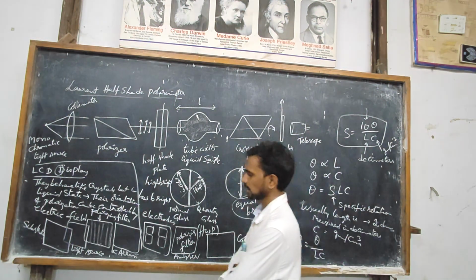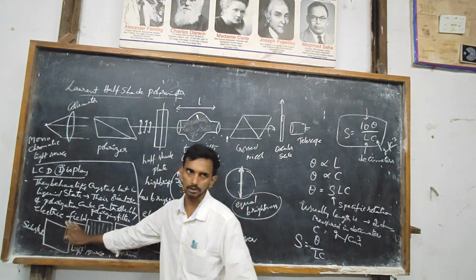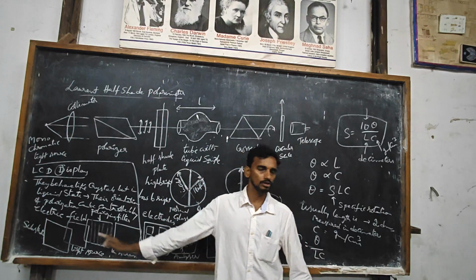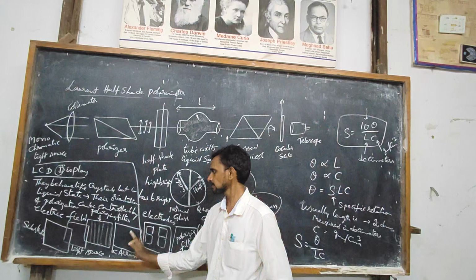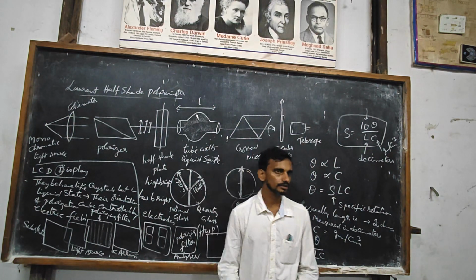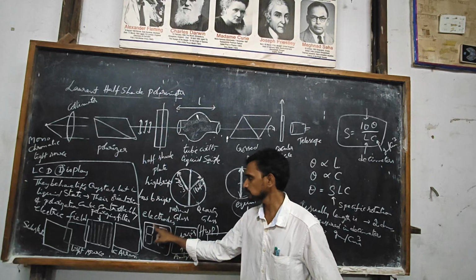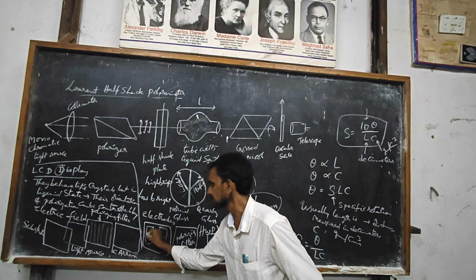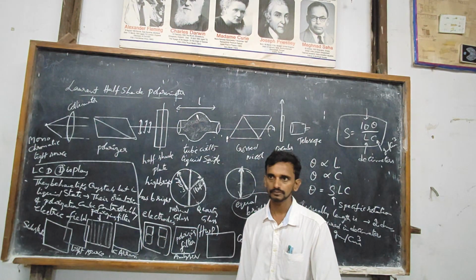So what is the overall structure? We have substrate, light source followed by polarizing filter. So we get polarized light. Next to that the liquid crystals and then electrodes. So when you apply an electric field to these electrodes, they try to tilt the liquid crystals in their location.